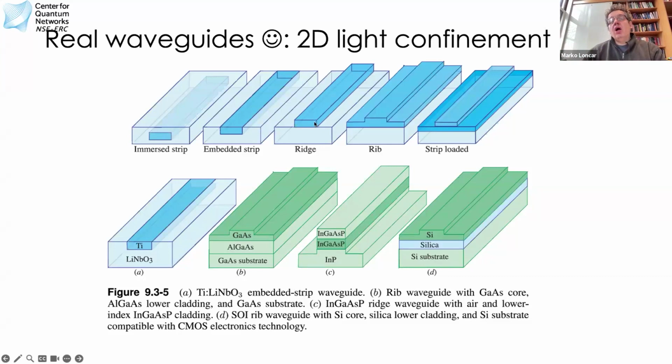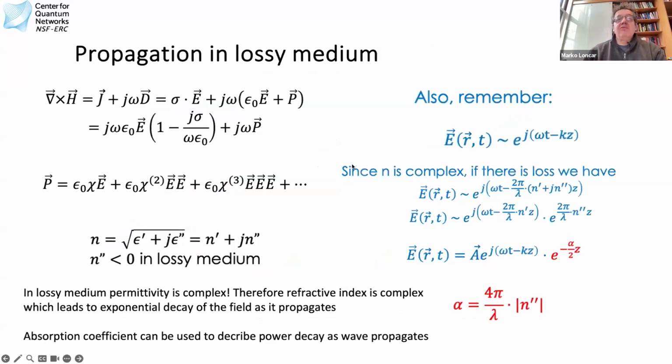But what if my fabrication process to make the silicon waveguide is not perfect, if I have some roughness? People can think about this and put in the Q&A: what would happen if I have some bumps, for example, or what if I choose a material that has some defects that absorb light or emit light, what can happen? So basically then we need to modify our treatment, and fortunately in most cases it's sufficient.